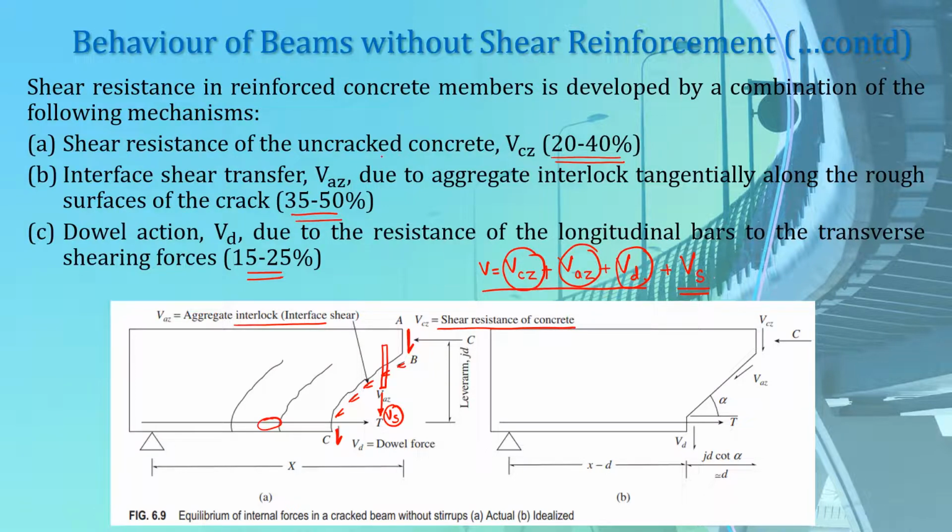So this shear resistance of the uncracked concrete is the simplest method of shear transfer by shearing stresses. This shear resistance occurs only in uncracked concrete or in the uncracked portions of structural members. So the interaction of these shear stresses with the tensile and compressive stresses produces principal stresses which may cause inclined cracking or a crushing failure of the concrete.